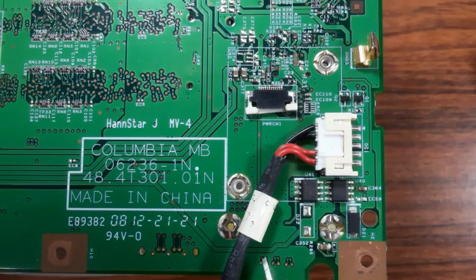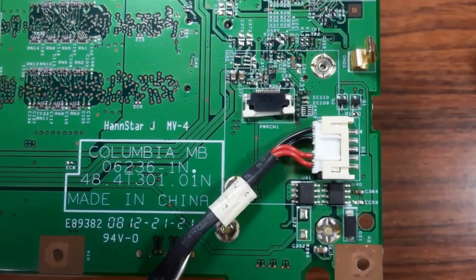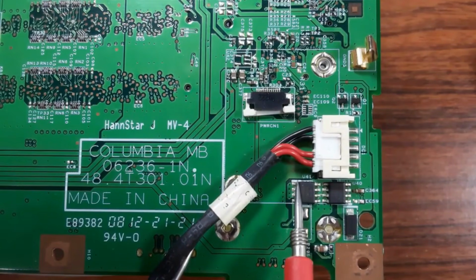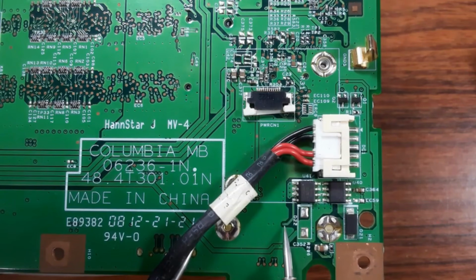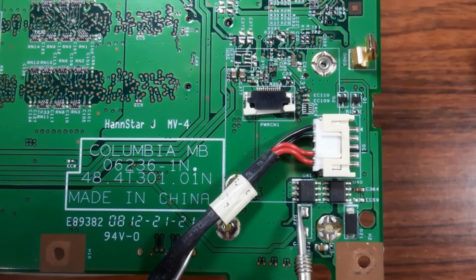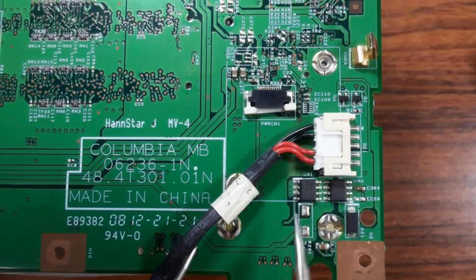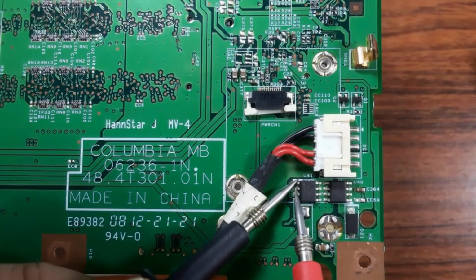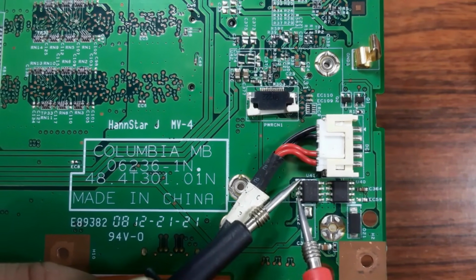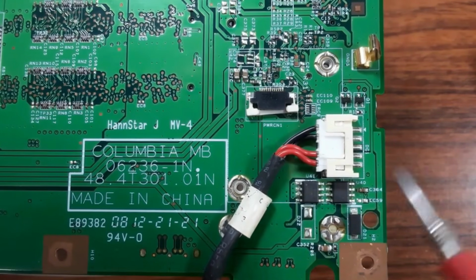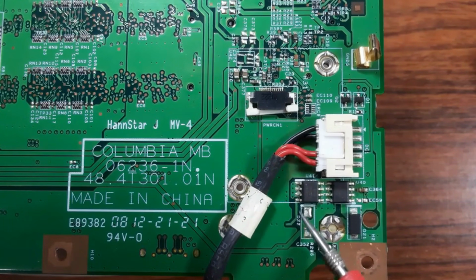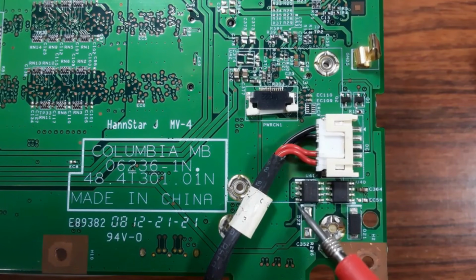But for example, for this Mosfet, we have here 3 terminals connected together with the same color. But this one, no. This one is connected to this bus, means this is the gate. These 3 are connected together. So let's check the first, the second, the third. But this, no, it is not connected with these 3. As you see here, we have this signal. This is the gate. Here we have the control signal. The control signal passes through this bus, and here we have source.